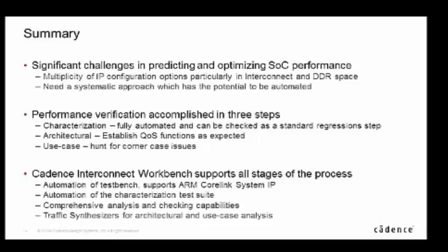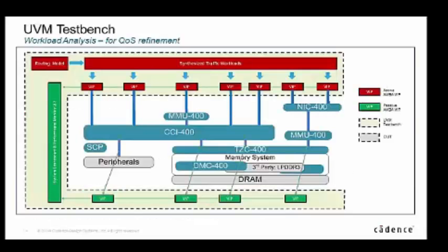A question as well. You talked about the refresh on the DDR, but I would have thought if you're trying to do performance, wouldn't you just switch that off and do it as if there wasn't any refresh to get your absolute numbers, and then know the impact? Yes, you could do that, and the tool will tell you the min-max latency, so you'll see the min latency in the periods when there's no refresh.